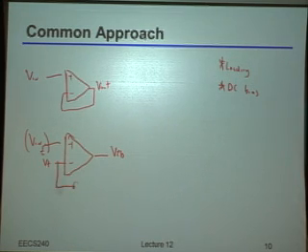Yeah, exactly. So I put a really big inductor here, like this, and let me label that L big. And when I say big, I really mean big, like, you know, a Henry or something like that. Okay, again, this is SPICE, so there's no problem with actually doing it. Okay, so by putting that really big inductor in, what did I do? Well, if you think about it, the really big inductor is saying, well, at DC, those two things are connected to each other, right? It's just a dead short. So that means the DC biasing will be correct. But at any reasonable frequency, especially if my inductor is really, really big, I'll basically have an open circuit between those two ports, right?